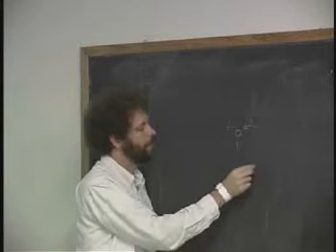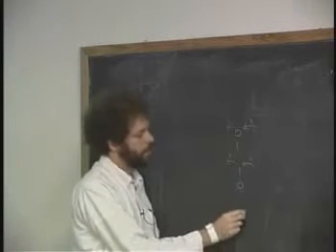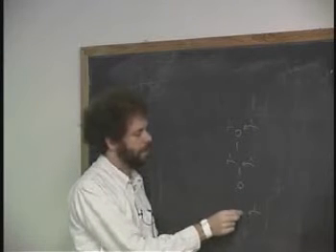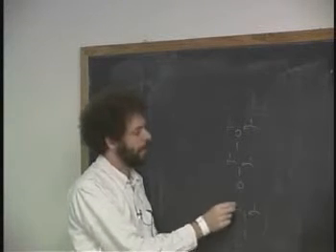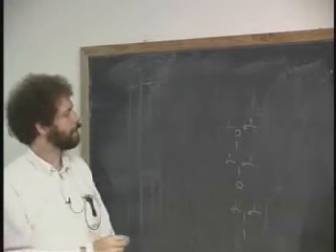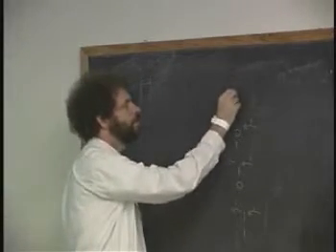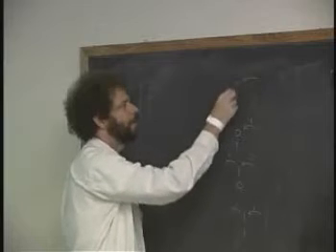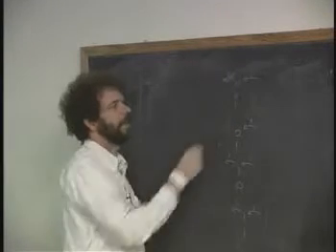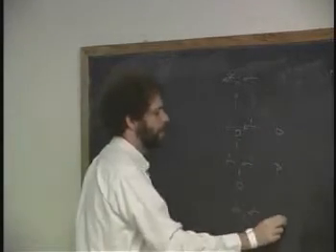Obviously, if a 1 and a 0 comes in and a 1 comes in, then I want to propagate out. What about the 1 and the 1 case? If a 1 comes in, should I propagate the carry out? Yeah, okay, so there's three cases. And the only one left is 0 and 0. Do I propagate then? Hopefully not, right? If a 1 comes in, then I eat it up, and I spit it out here, but I don't propagate it out the output. So here I propagate, propagate, propagate.